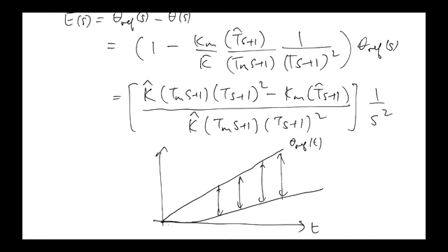So we can't meet our control objective with open loop control unless we know the model exactly. And you never know your model exactly. You've seen it with your own eyes. The two motors are different from each other, even though they come from the same manufacturer. Try it. Simulate, the observed data for both motors will be slightly different, which means you need to use slightly different parameters to match the observed data exactly. But we just want to use one model for both motors. So this is the problem with open loop control.